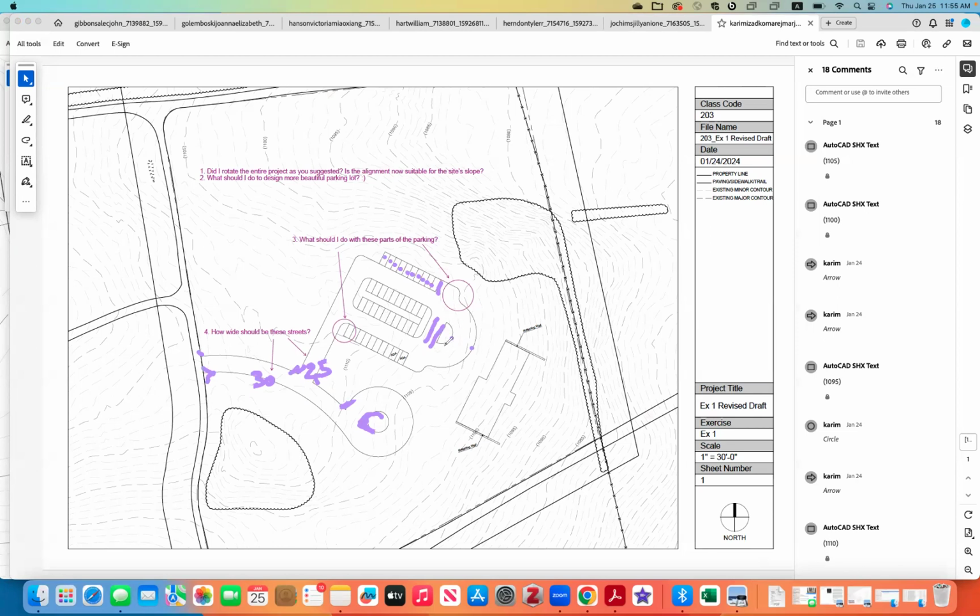Because when you limit this to 1 lane, people will know, okay, I am only supposed to drive here if I want to drop some people off. Otherwise, if this is too wide, folks, when they come to here, they might basically zoom through that space as well. You want to try to limit that. So the suggestion would be to make this area smaller, and by going into like here, only leaving 1 space, okay?